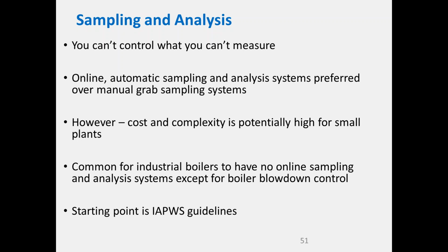So you've got to be pragmatic and say, what do you absolutely need? Is it going to generate me some value? Is it going to protect me from a very high cost type problem, or is it just a nice to have? So what we normally find for industrial boilers is that there are no online sampling analysis systems except for maybe boiler blowdown control, or maybe some kind of condensate dumping system.